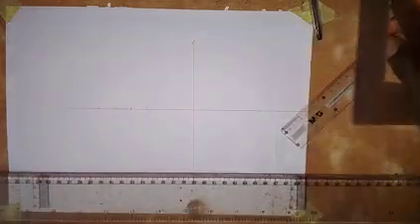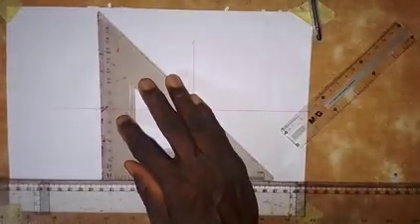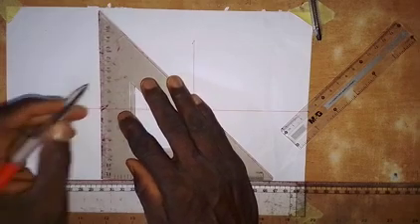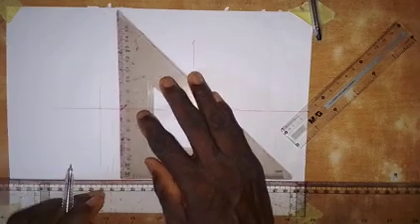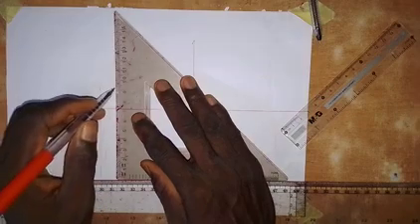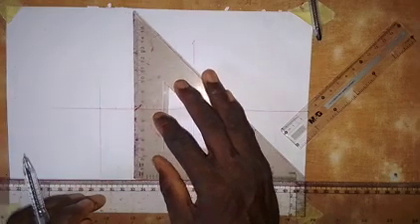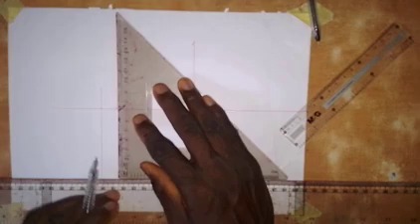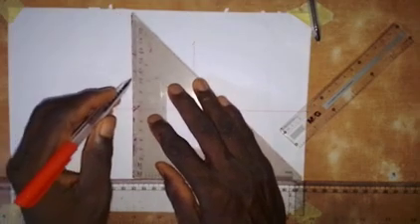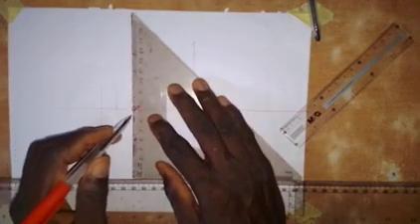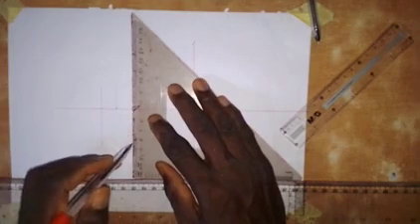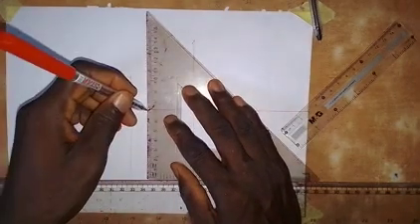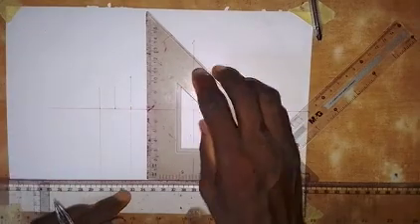So on all these distances that we have taken on the horizontal, we have to draw a vertical line on each of them. So we draw a vertical line down, and here also. I'm not going to draw a vertical line here, but I will take it up. I'll take it up here, just a short line. Then here I'm going to draw a center line down here. So this is a center line. Then here also I will draw a vertical line up here like this. Okay, so this is okay now.